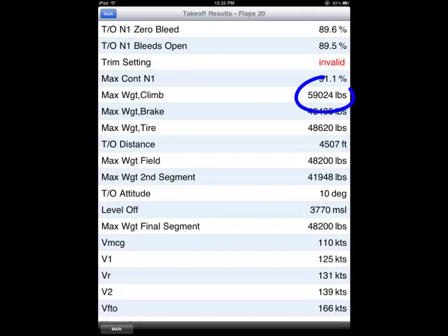Do not be concerned with max weight climb values that are higher than the max weight of the aircraft. Since this is a certification value based on density altitude and not structural limits, many manufacturers display the full value, possibly anticipating a weight increase for the airframe. Also note, max weight climb has nothing to do with the climb requirements for a given obstacle or airport. Press the main button on the lower left screen to return to the main screen.